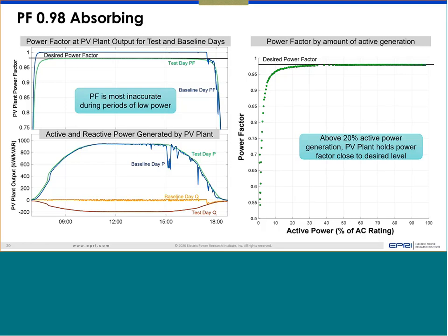It depends on their islanding detection mechanism. One islanding detection mechanism is to push a reactive power to see whether you can push the voltage or not. So if an inverter uses that mechanism of islanding detection, then you may see that with a certain time interval, VAR goes up and then comes back, maybe to zero or the opposite direction, then again goes up and down.